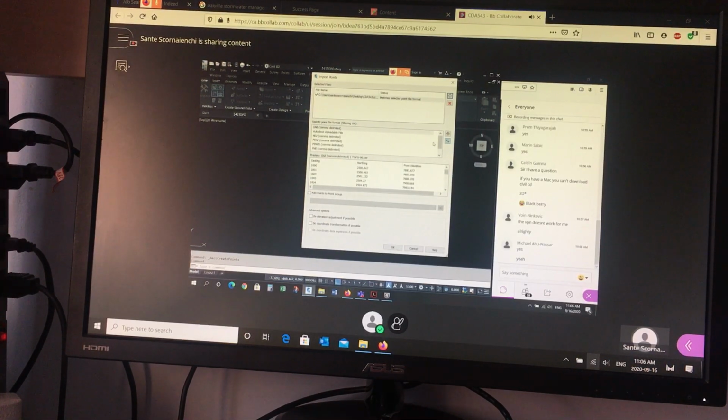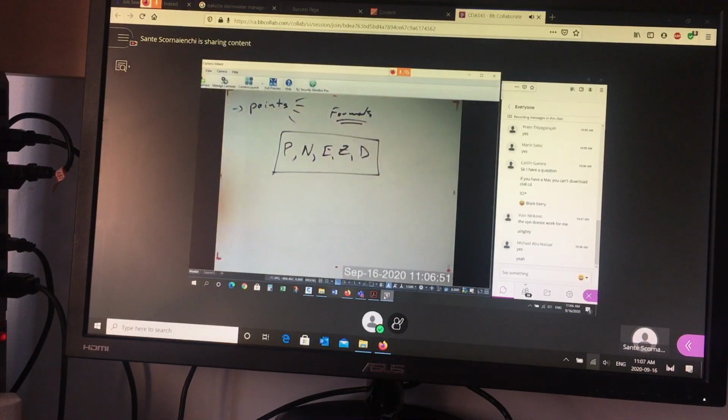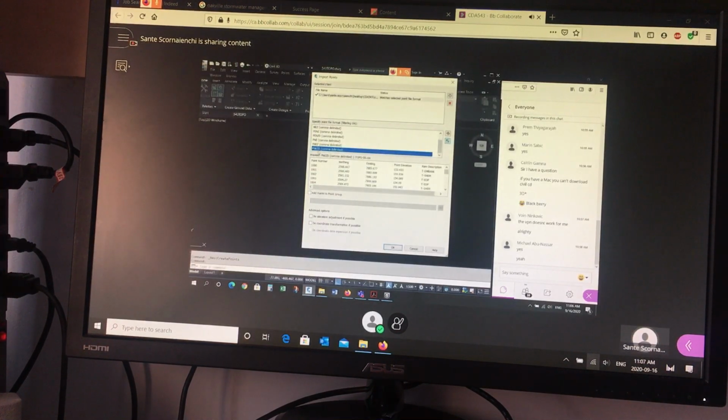Then, this is the critical part. In this next white space, you have to choose the file format. And this comes from that list that I showed you, tool space settings. It's near the bottom, always the last one at the bottom. But please be careful. Use this file format: PNEZD, comma delimited. You can see it's spelled out, comma delimited.